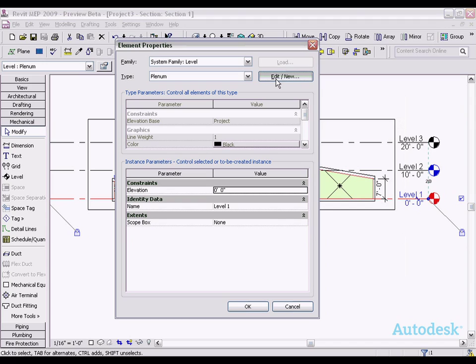So if we've gone ahead and set it at 4 feet, we can see that we had no impact on this room here, because again at 4 feet, which would be right about here, we're going to hit bounding elements in all directions. Now if we move over to this height, we'll see that at 4 feet we projected sideways, and we actually hit this roof as a bounding element, which is why we're going to see this gap exposed right here.